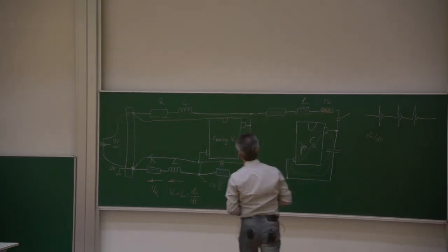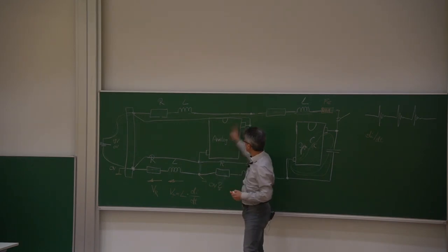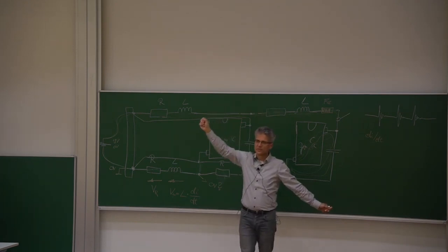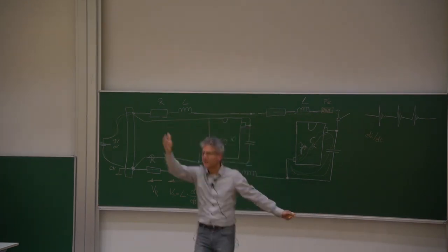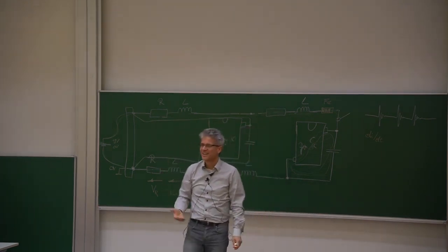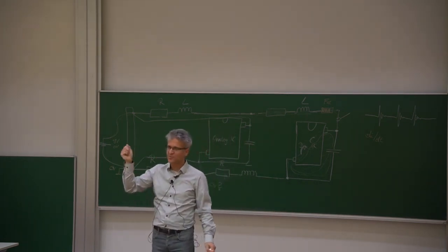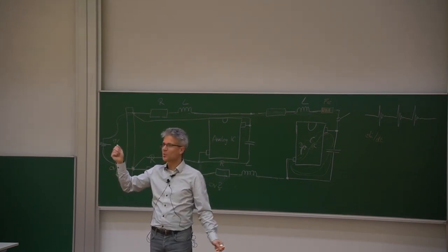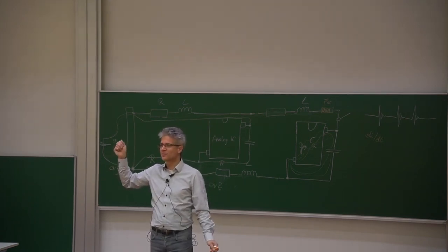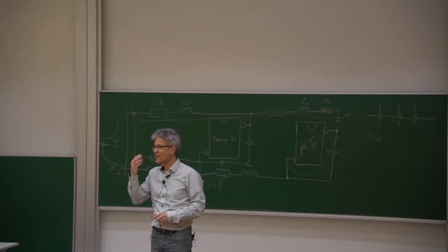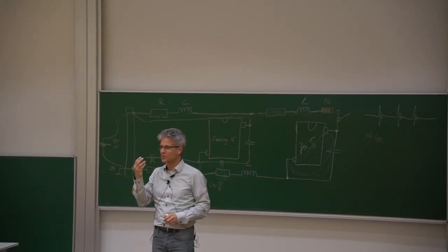There is a reason why I have drawn chips with this configuration, VDD here and ground there. Those pins closer together. Yeah, put the pins closer together. Any idea why they have placed these VDD and ground pins in the most stupid way they could have been placed, especially for the old-fashioned 74 high-speed CMOS designs? Because it was done like this. Yeah, but there must be a special reason why, from the EMC point of view, it's completely stupid.